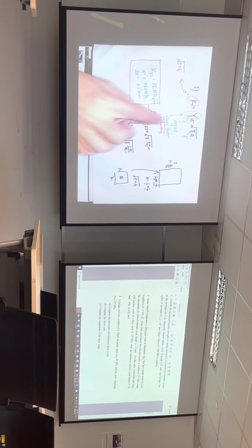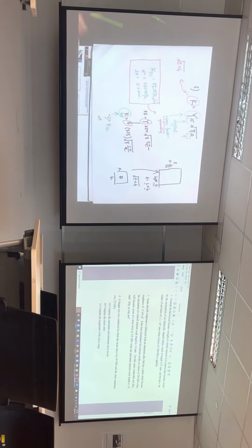So this question really is an application of here. The first part is for you to find the Y because both components are the same. Just trying to give you an arbitrary example. Later, for example, you have another batch of materials with a smaller crack, and you try to load it with a higher stress, and check whether it will fail or not based on the material property. So this is calculation. I did not do the calculation. If you have done it, you will find that this value is higher than 35, so it will fail.